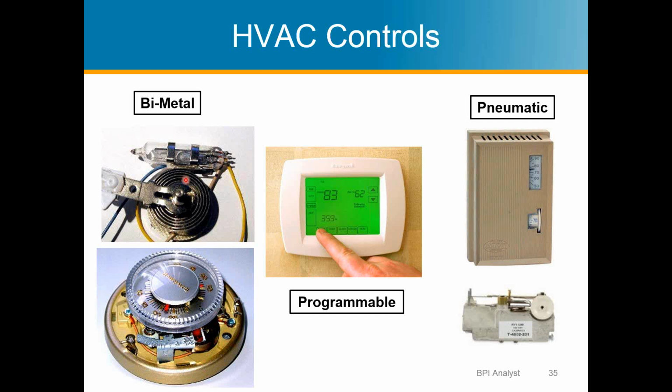So what happens when the temperature changes, one will expand at a faster rate than the other one, and because it's coiled and one's growing faster than the other one, it will turn itself. So it's kind of curling itself as temperatures change. So when you talk about bimetal, that's what it's doing. And a lot of bimetals will have a mercury switch, and that's what this is here. So this little slug of mercury,